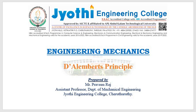Today I am going to discuss with you a topic in engineering mechanics which is called D'Alembert's Principle. We all are familiar with the conditions of equilibrium in statics, that is sigma Fx equal to 0, sigma Fy equal to 0, sigma M equal to 0. So these conditions of equilibrium for statics mainly we use for solving the problems in free body diagrams as well as the structural mechanics. Similar to that, we can develop a condition of equilibrium in the dynamics also. So that is based on Newton's second law.